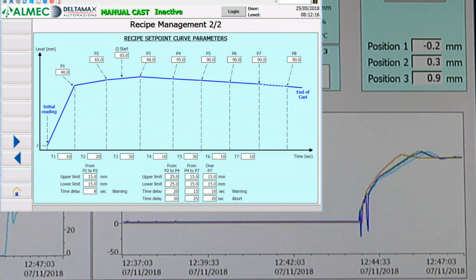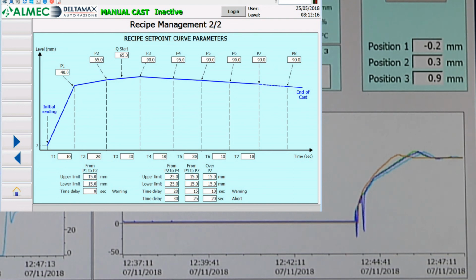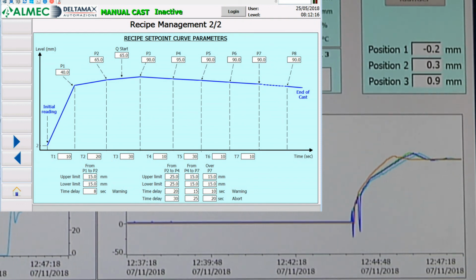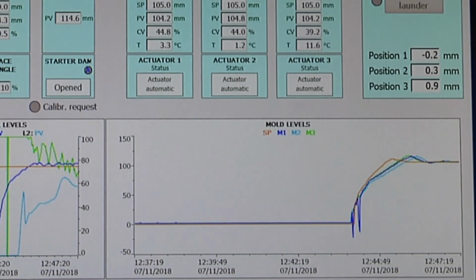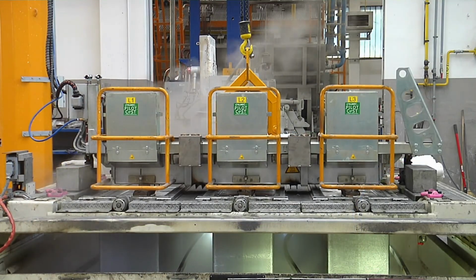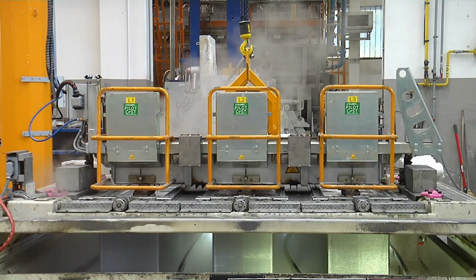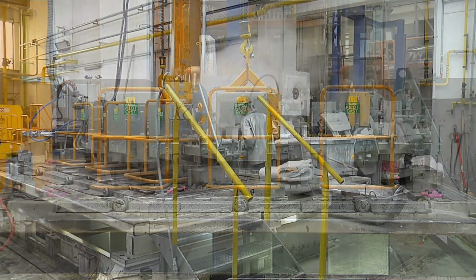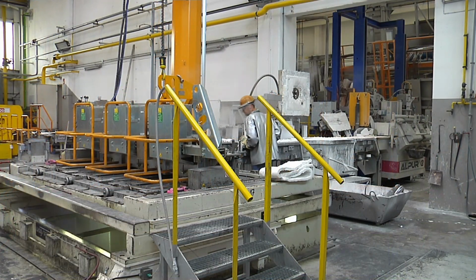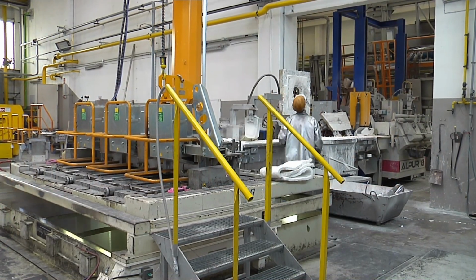The system awaits that the length of the platform be greater than the furnace stop quote, calculated by subtracting a value from the cast set point position, measured based on the number of slabs used and the geometry of the slabs themselves. Once the preset position is reached, furnace descent is commanded, sending the corresponding signal to the panel.